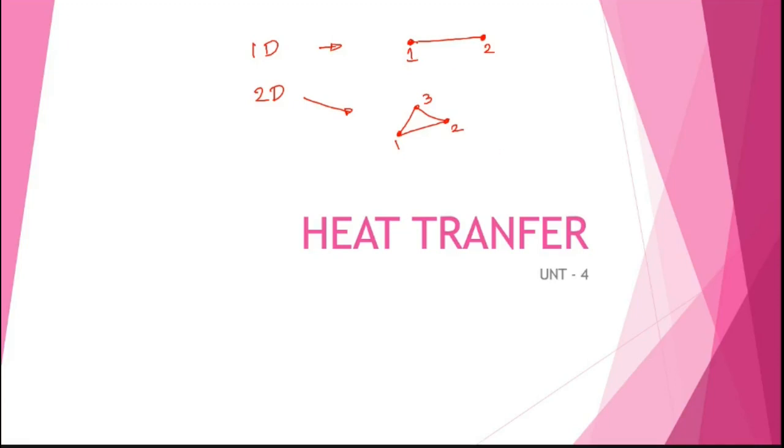Let me consider this is a bar element. So what is your stiffness matrix K? Can anyone tell me what will be the stiffness matrix K? AE by L [1 -1; -1 1]. Yeah, very good. AE by L [1 -1; -1 1].